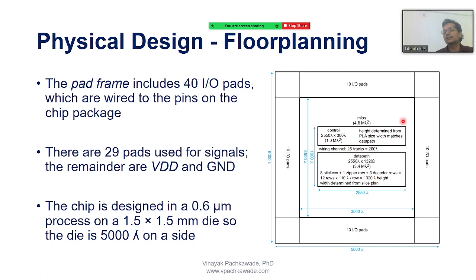For example, using the NAND NOR logic, you would want to create the flip-flops or latches. Using latches and flip-flops, you would create the layout of counters, shift registers. Using the layout of those counters and shift registers, you would want to create a logic for random access memory, RAM, or read-only memory, ROM, etc. So this is how you start with a single cell, inverter, NOR, NAND, and then you keep on creating, by interconnecting them together, a bigger logic.